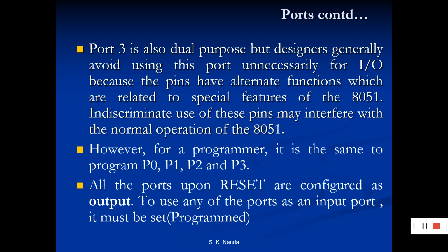Then port 3. In this port, functions are similar to other ports except that logic 1 must be applied to appropriate bit of port 3 register. It is also dual purpose, but designers generally avoid using this port unnecessarily for IO because the pins have alternative functions which are related to specific features, or I can say special features of 8051. Indiscriminate use of these pins may interfere with normal operation of 8051.